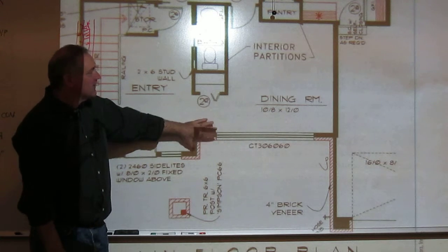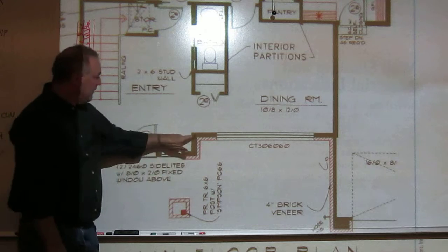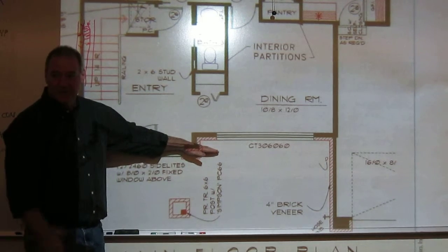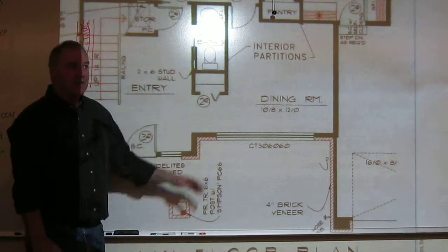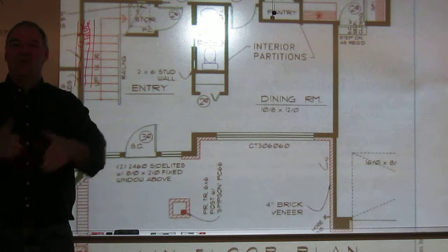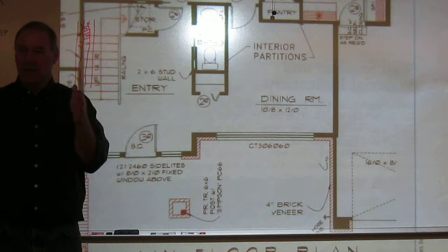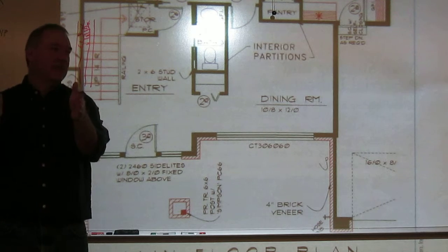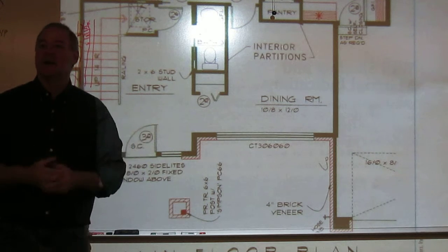This is more of a commercial or architectural feature. You just have two object lines representing the edge of your finished surface. Again, we don't draw the drywall in there. We just add it as part of the wall component. We're not going to draw 3.5 inches, another little line 1/2 inch off, because we're not going to see it at the scale we print anyway.